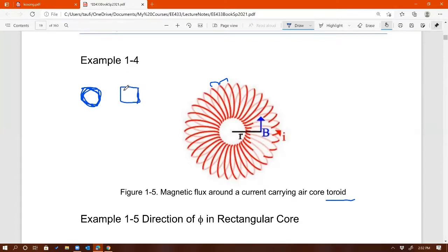If you have a rectangular cross-section on a donut-shaped toroid core, good luck. That's really tough to wind. It's easier to make a perfect winding though, because you can apply force around the edges as you make the turn. But that would definitely make calluses on your fingers. What else though? So that's right, more difficult to wind.